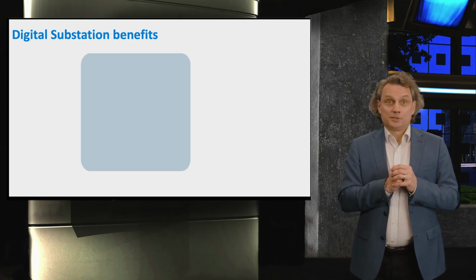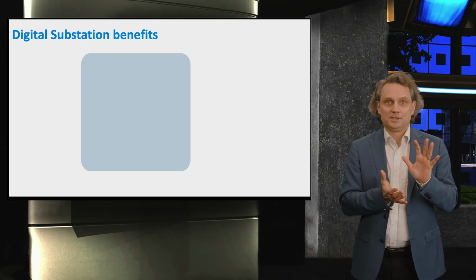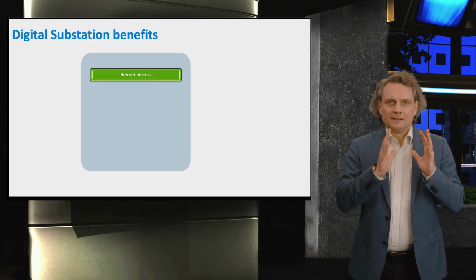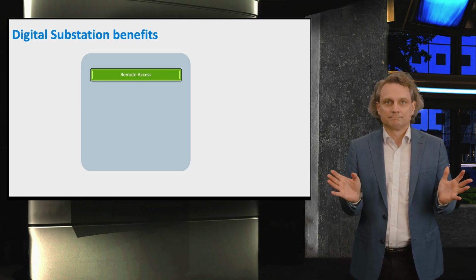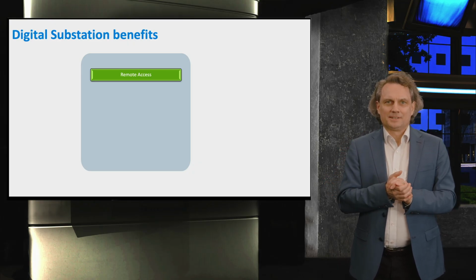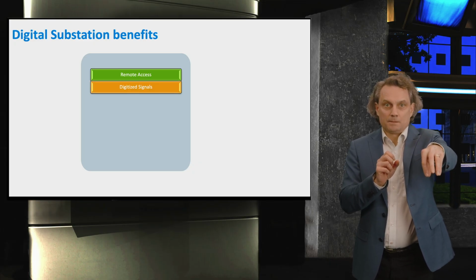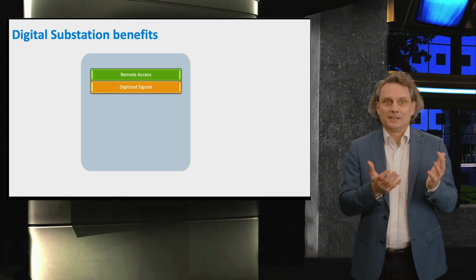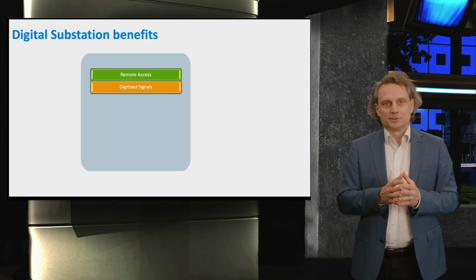We have already come across many of the benefits of digital substations, but let's recap these benefits here. To begin with, digital remote access is fast, flexible, and saves time. Another benefit is that the electrical signals are now digitized right at the source, maybe with a non-conventional transducer using fiber optics and with less copper involved. This makes signal processing and handling much simpler and more robust.